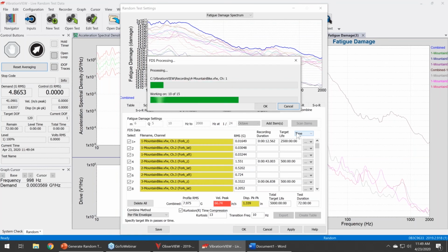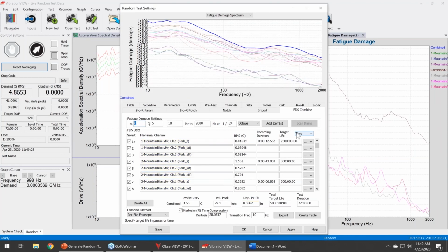So that in the end is what the Q value is setting: the Q of the single degree of freedom oscillators used to generate the single or narrow frequency waveforms. This whole calculation operates under the premise that there is a resonance at each frequency.